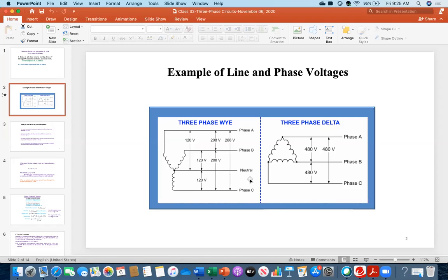So this means that you are unsafe. You don't have the neutral line, and because the neutral line got heated and burnt off, so that has been disconnected from the grounding system. So you are fully unsafe. So that is one thing.